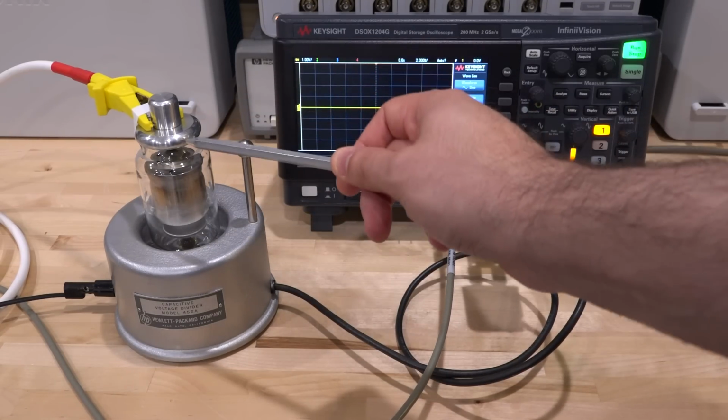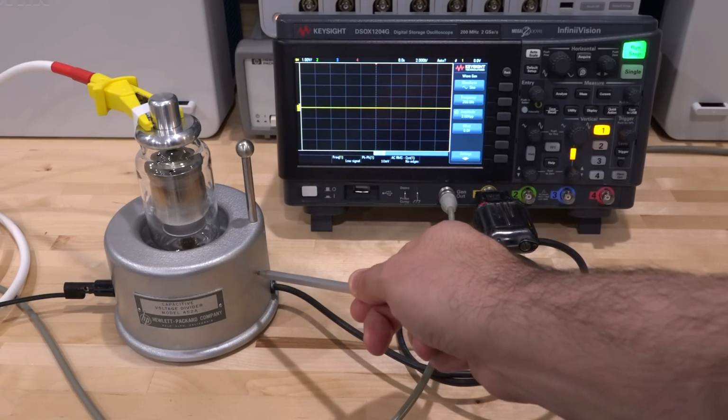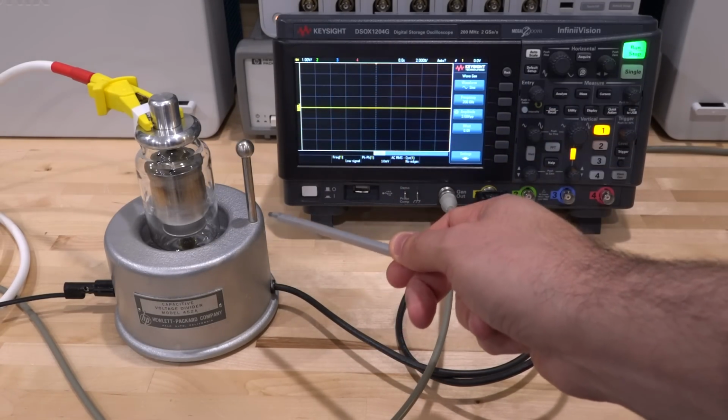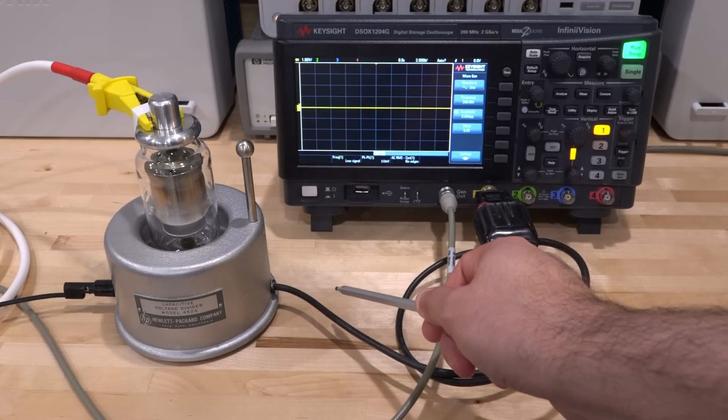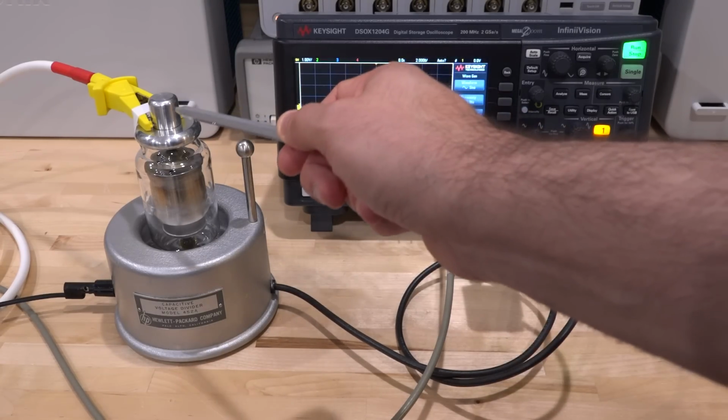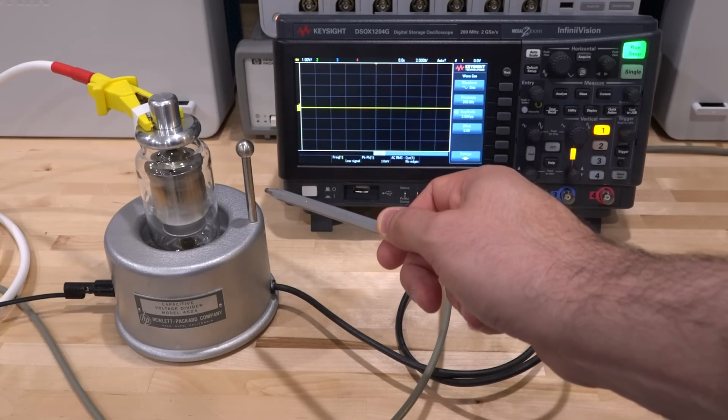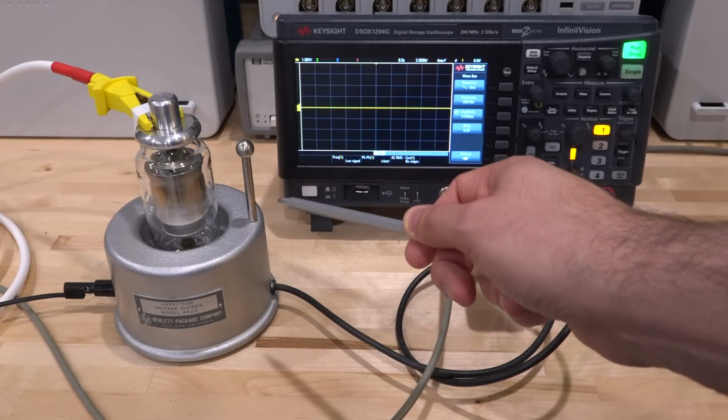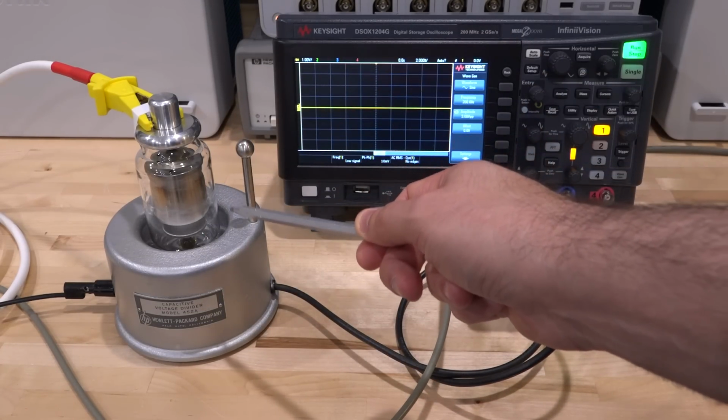It uses a vacuum tube capacitor with a much larger capacitor in the base, creating a division ratio of about 1,000. That means that the voltage appearing over here is just the AC version, whatever you put up here, but divided by 1,000. Now this is very nice because it has a very high breakdown. I can go to more than 25,000 volts on this.